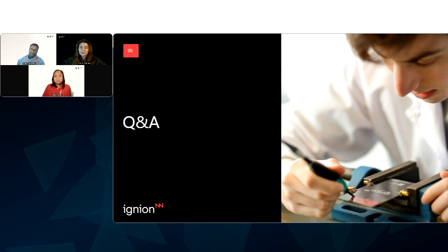So the antenna will undergo shock and vibration, temperature testing also, because most electronics will work in the region of minus 40 degrees Celsius to 85 degrees, right? And then seeing if the antenna is able to withstand those sort of temperatures. And for epoxy glass, FR4, that's usually not even a problem.